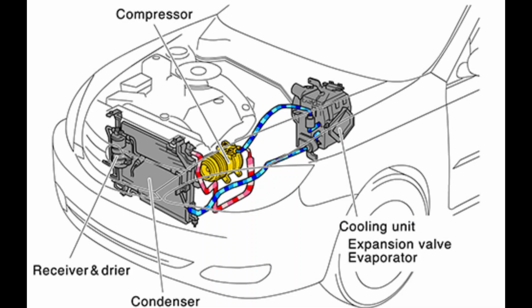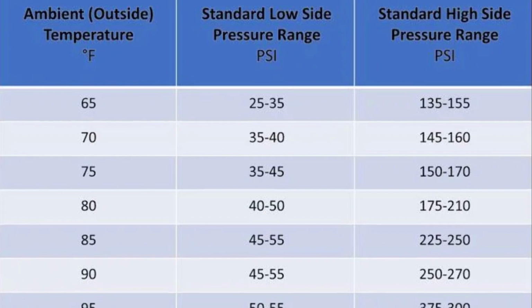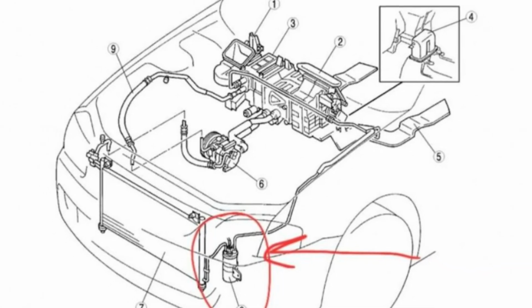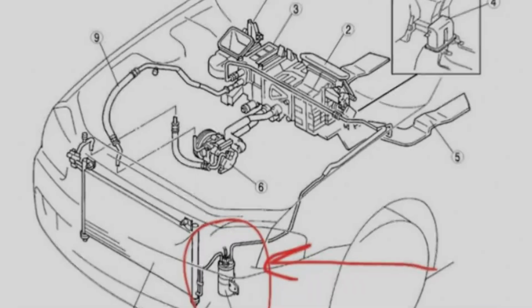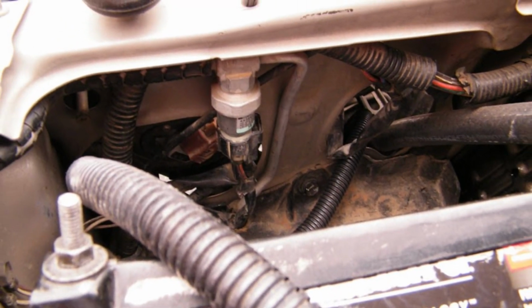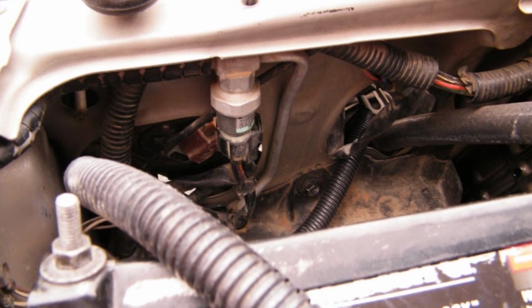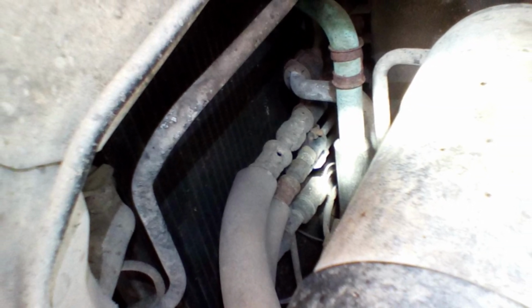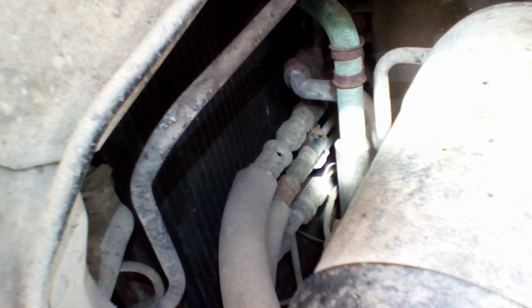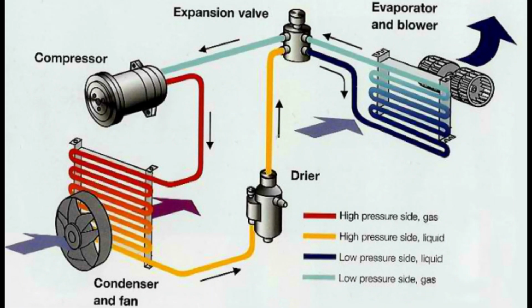The AC pressure switch monitors the pressure levels of the refrigerant in your car's air conditioning system. There are usually two pressure switches in the system, a low pressure switch and a high pressure switch. The low pressure switch ensures that the refrigerant pressure doesn't drop too low, which would prevent the compressor from functioning properly. The high pressure switch, on the other hand, protects the system from excess pressure, which could cause damage to components. When this switch goes bad, it can lead to a host of problems with your AC system.